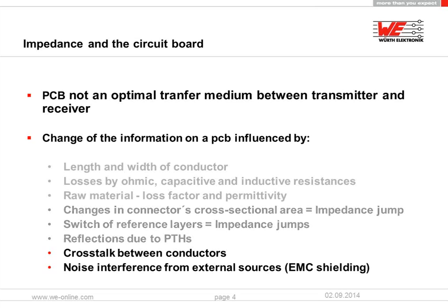This helps to avoid interference disturbing the signals. As you can see here, this is folded into the package, using this extreme possibility of miniaturization, and at the same time having a shielding possibility in between the single modules. This is quite a nice option using flex rigid.